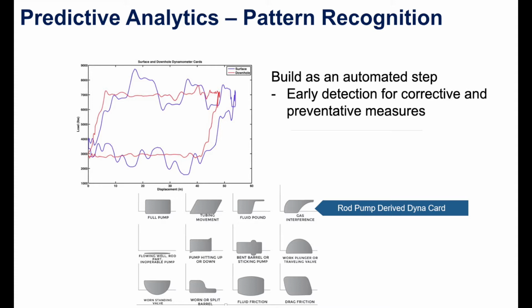Well, we're also beginning to look for other patterns. And here, when you look at the performance of a rotating artificial lift pumping unit, our pattern is a lot different looking, right? The information that we get from the sensors on the pumping unit still gives us an idea of what is good performance, i.e., the rod pump is performing and we are lifting fluids to the surface, versus what other kinds of problems you can have.